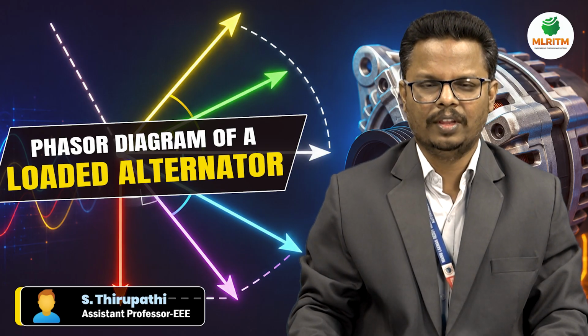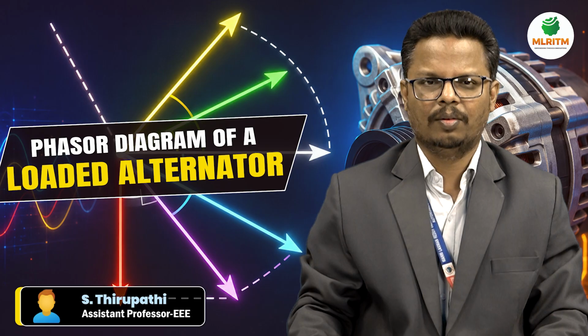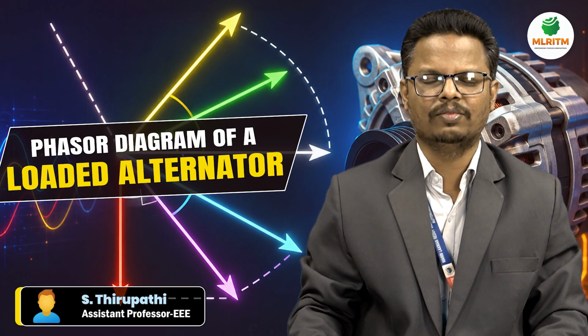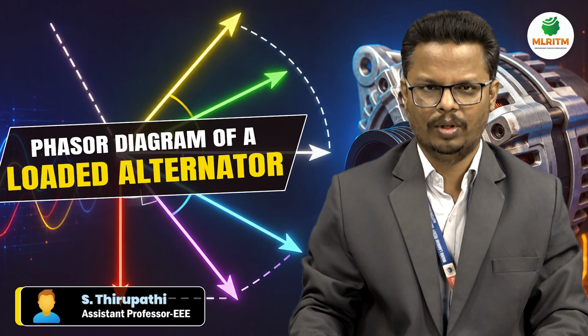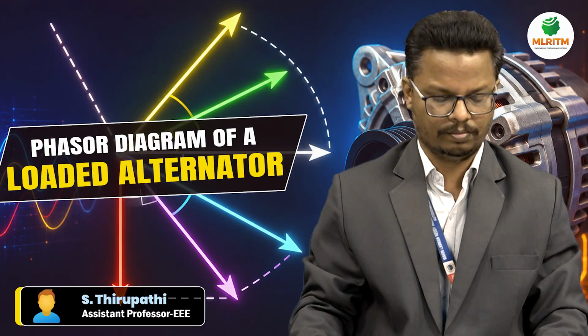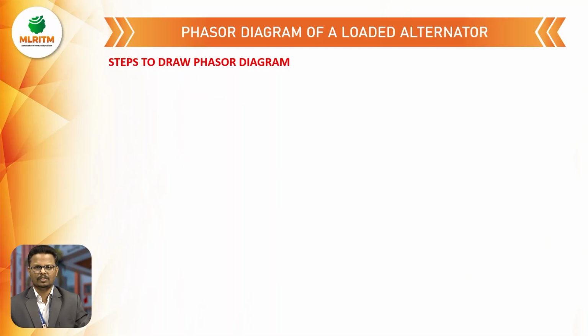In alternators, basically we take the reference as current, but in normal phasor diagrams we take the reference as voltage. So now we will discuss the steps for the normal phasor diagram. Here I will draw, you will see. In this normal phasor diagram, I am considering the voltage as the reference, that is V.